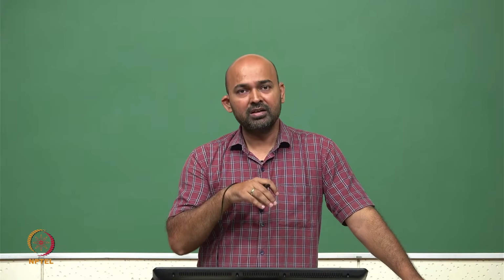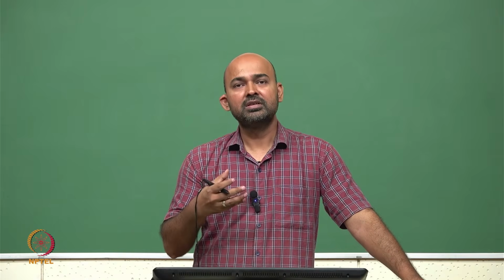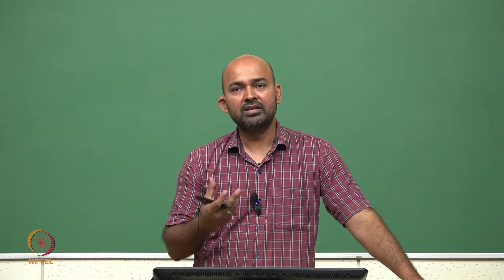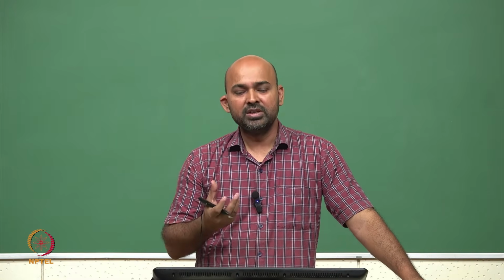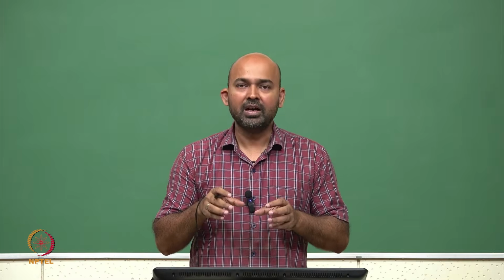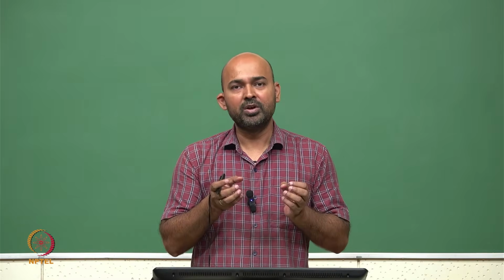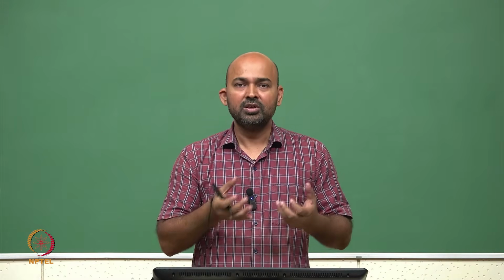So we have here R of the wire and C of the wire. This R and C combined give the parasitic resistance and capacitance, which reduces the speed of the overall circuit. So let's see how we can model the wire as a lumped element model to analyze how much delay it causes to the actual speed of the circuit. Lumped element model.